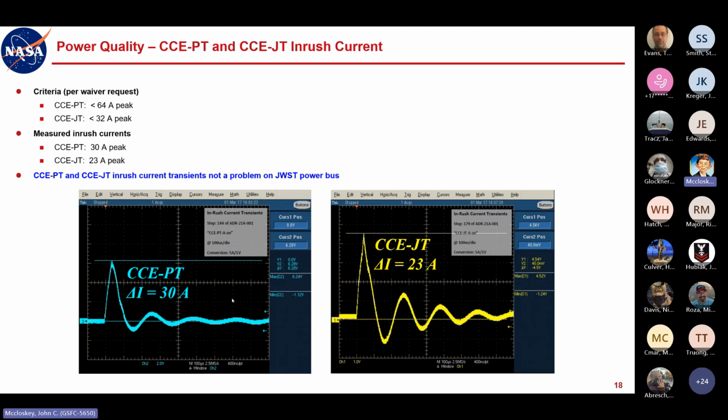So what I take from this is that the actual source impedance on the spacecraft was different, or a little bit lower than maybe what they used at unit level, or at unit level maybe they used a capacitor network so that they got a worst case current, which is exactly what we want. But I would say the actual source impedance of the spacecraft is probably a little bit higher in this frequency range, so that it's limiting the current a little bit.